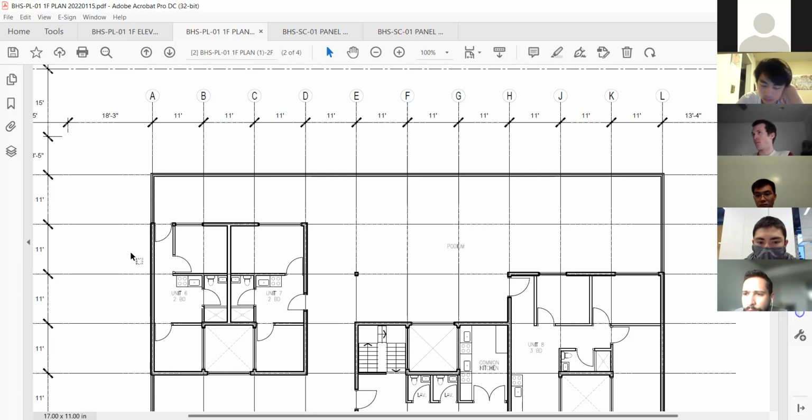Except for the overlapping part that's going to have to be a roof, it doesn't have to be waterproof. It could be hardwood or something like a deck, right? But because of those two blocks that are actually a building on the first floor, you're going to have to waterproof the whole deck. Yes. You only need insulation right where the arrow is, those two squares. There's no need for insulation anywhere else, right?